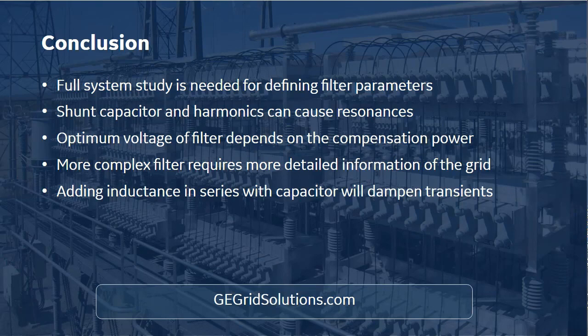So for example, a C-type filter, and then you put a shunt reactor in parallel to the filter and compensate the fundamental frequency power of the filter by the shunt reactor. So it means that you will have an equipment or gadget which has a zero reactive power output to the system, but it will still filter the harmonics. Okay, so this is one also thing that is increasing.